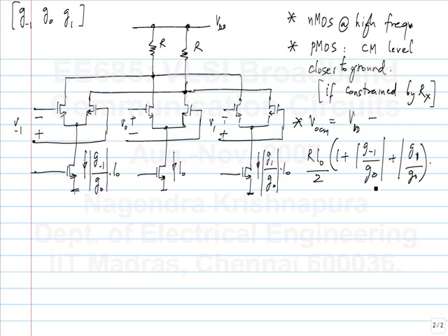Let's say you have to realize large values of G minus 1 and G1, and if you have more taps, they all sum in an absolute sense. You have to sum the absolute values of the normalized taps. Then you can reduce the value of I naught or reduce the value of R and keep the transistors in saturation region. What will be the disadvantage of that? Less... why? Yeah, that could be one reason. Actually, even more importantly, the signal swing is less. You are sending out a smaller signal.